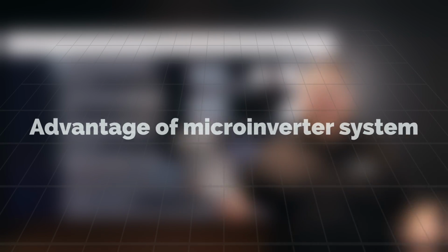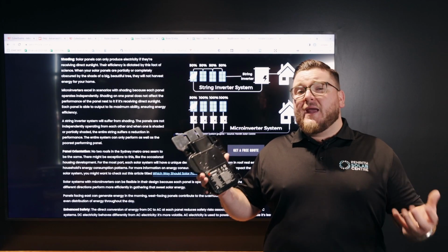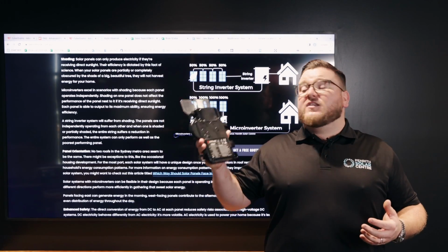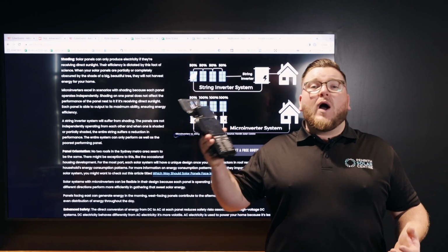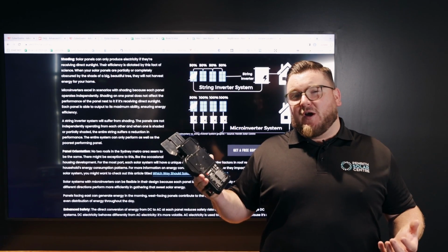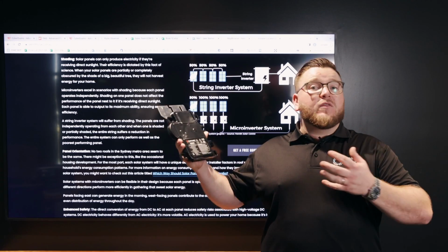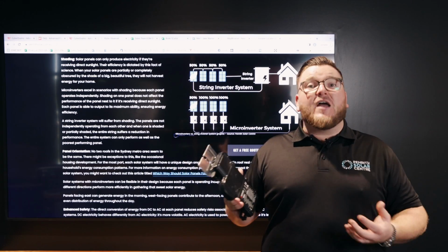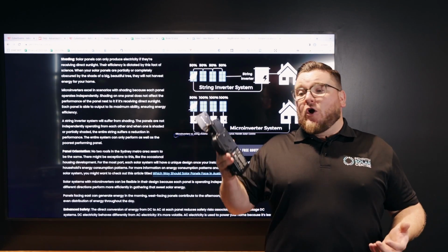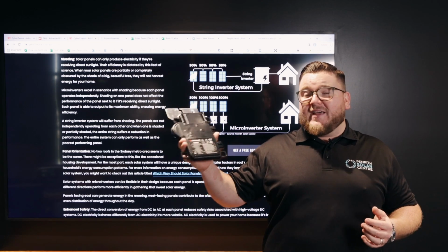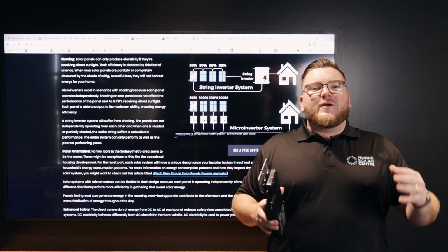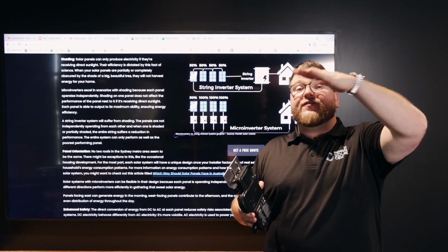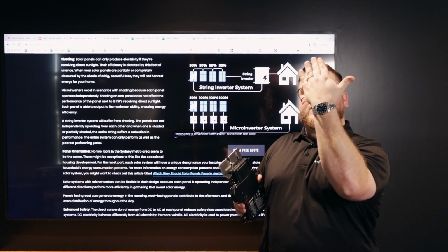One of the advantages, of course, of the Enphase microinverter, and what most people think they're used for, is for, of course, shading. It is true that if one panel is shaded with an Enphase microinverter, the other panels on the site or on that roof face are not actually affected. So whilst this little microinverter takes a little kip under the shade, the rest are working at full pelt, which means they're going to be facing all different tilts and orientations.